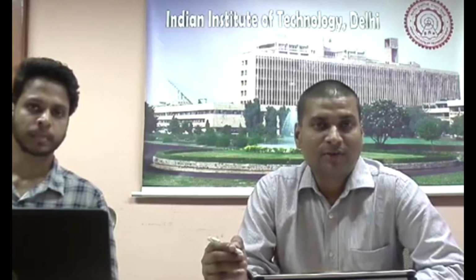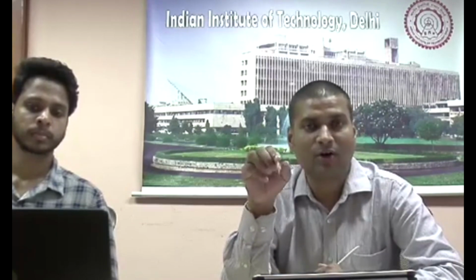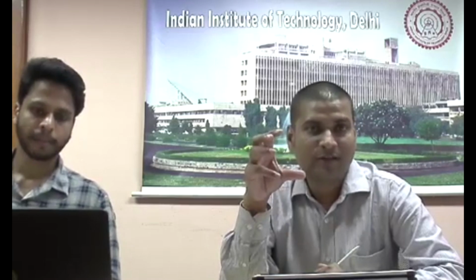But there are advanced theories. For example, we have what's called Cosserat theory of elasticity, in which the unknowns, when you solve the deformation problem, are not just the displacement of every point of the body, but every point of the body has got some rotational variable also associated with it. So every point in the body has got displacement u as well as a rotation variable associated with it. The way to visualize this physically is that there could be a body which has got some microstructure in it.